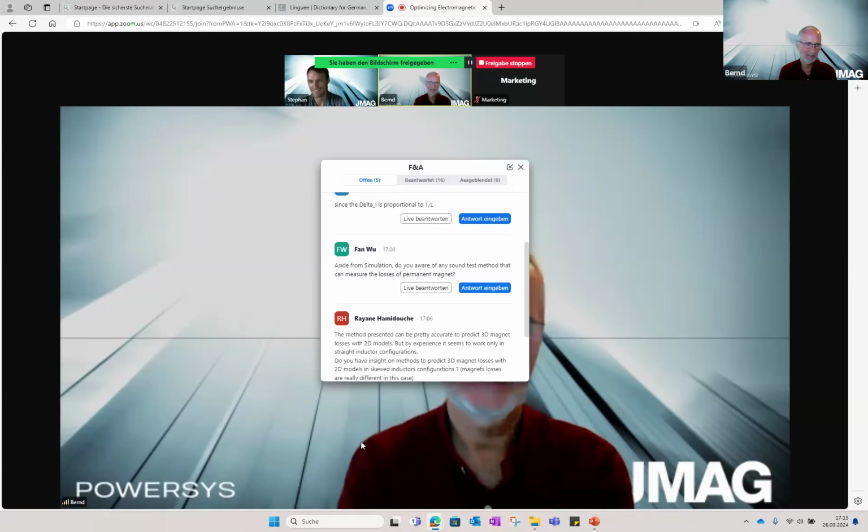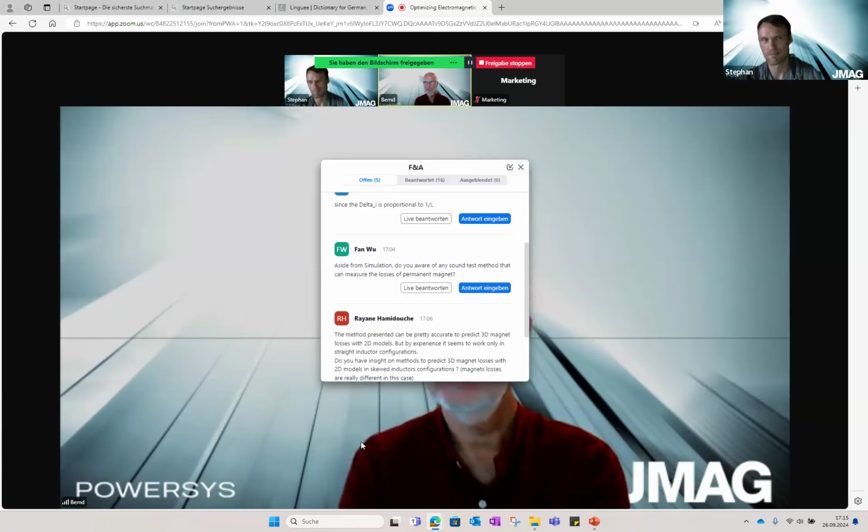I mean, the answer was given at the beginning already. If 70% of you are agreeing that using 3D is probably the better approach, this answers the question. In case you have any specialties in the magnet, like different conductivity regions, which also exist. You know, we have magnets with a grain boundary diffusion, where the boundary has a different dysprosium content than the middle layer, and this touches the conductivity as well, and also other methods. This, of course, cannot be solved by any analytical approach.